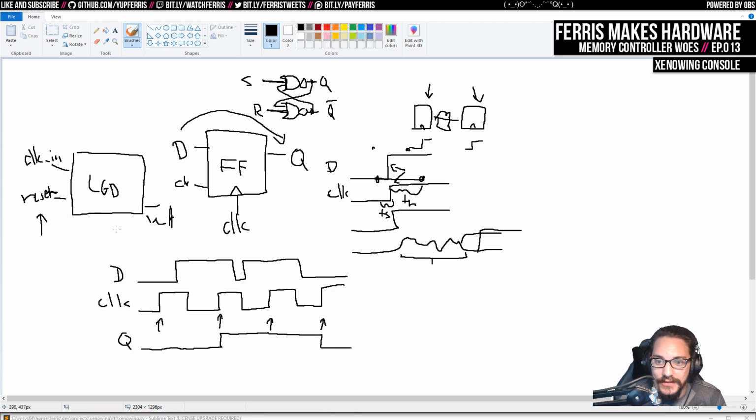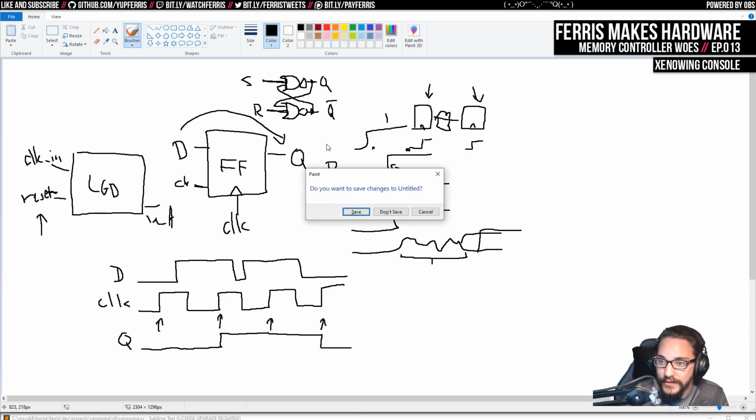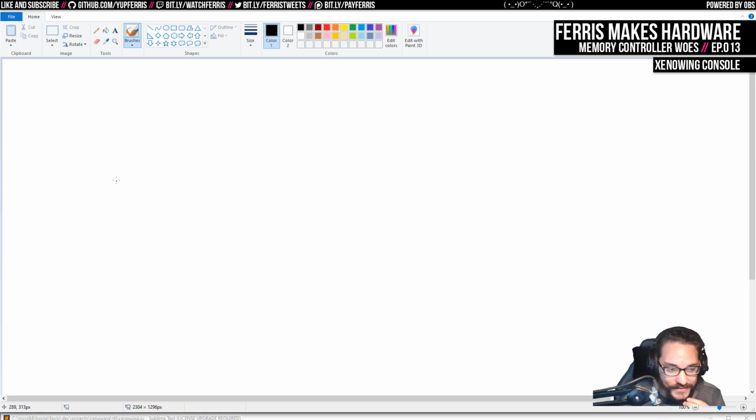The other thing that we need to do is make sure that once we get a reset that feeds into all of our flip-flops, that reset signal isn't going to be raised within any of these periods near the clock edge that are going to cause some trouble. The way we do that is actually fairly simple. We use what's called a synchronizer. This is a general thing you need to know when you pull any signals into your chip: how to synchronize them to your clock.